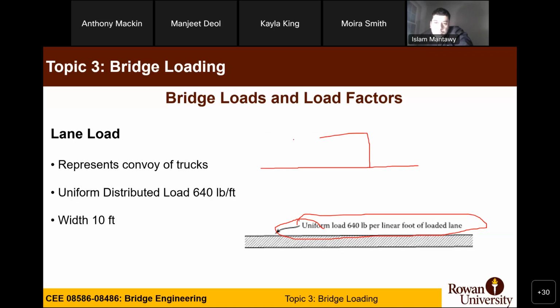So if you have the main truck in the longitudinal direction, you assume that you have a convoy of trucks before and after and even underneath, right? Because to get the same effect of the typical trucks on the bridge, correct? Okay.